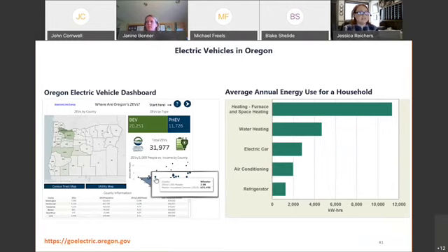So in fact, the challenge is not about how much electricity we need to power EVs, but more about when and where EVs are charging. Most EVs charge overnight, often plugging in when the owner arrives home, which adds significant electricity use, often at the time of highest overall electricity demand. Most EVs can be scheduled to start charging at a later time, and often these vehicles will not need to be charged the entire evening to meet the driver's needs. So utilities are looking at ways to stagger charging events to reduce the initial demand of all vehicles starting to charge at the same time.